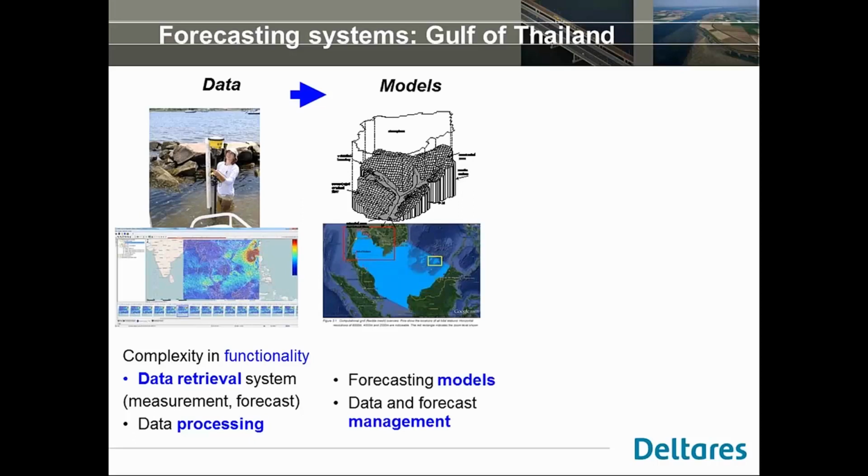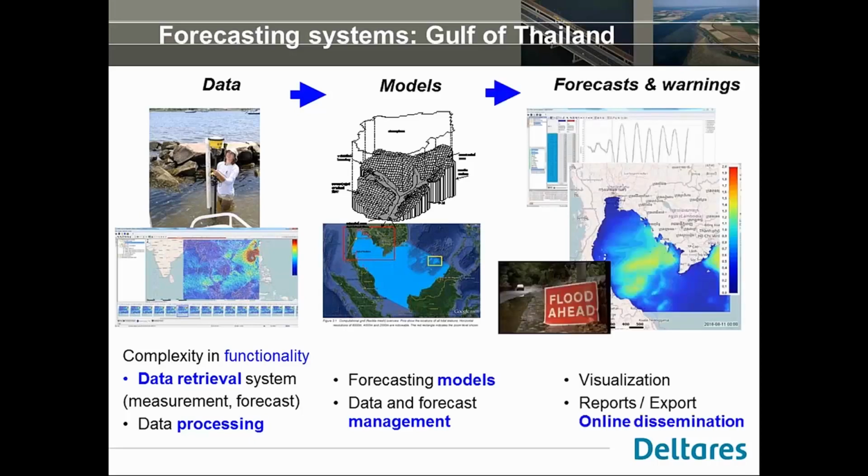And all the imported data are pre-processed by Delft-FEWS into the correct format of each model. Then those data are fed into the model and the model simulation starts. All the models running in forecast mode are scheduled according to a certain time interval in order to issue the daily forecast. So there is data and forecast management inside the Delft-FEWS software.